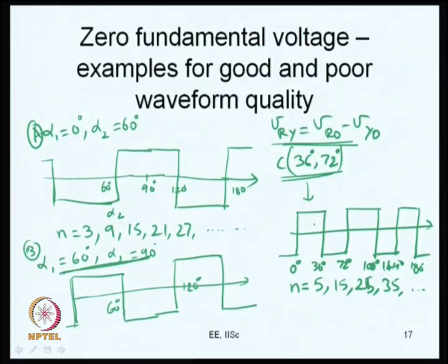So VRO has a fifth harmonic and VYO has a fifth harmonic, phase shifted by 120 degrees at the fundamental frequency. So you will get a resultant fifth harmonic in VRY. The voltage that you end up applying to the motor will be a big fifth harmonic waveform, instead of a zero or very low fundamental; you end up applying a very large amount of fifth harmonic.